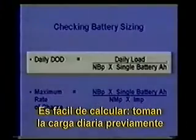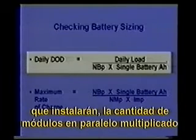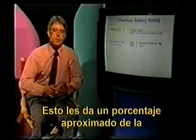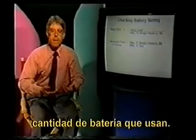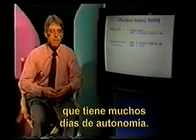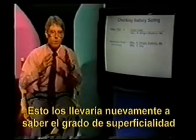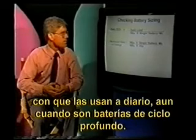Easy to calculate. You take the daily load that you've previously calculated and divide that by the actual full capacity of battery that you're going to install. The number of batteries in parallel times the single battery capacity in amp hours. By doing this calculation, you'll get an estimation in percentage of the amount of battery that you use. This might be as low as 10% for a system that has many days of autonomy. So that would bring you back to knowing, even though you're using a deep cycling battery, how shallow you're actually using it on a daily basis.